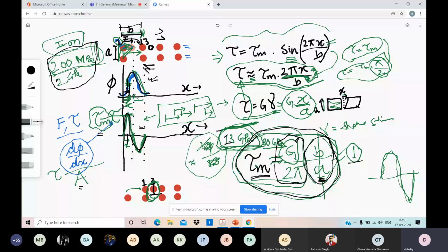And typically, if you see the structural steels that are used, which contain carbon, which gives additional strengthening compared to iron, there the typical yield strength value is 300 to 500, 600 MPa. Above 600 MPa, it is considered to be high strength. But to cause plastic deformation, you need a stress of 13 GPa as per this derivation. And then I asked, what causes this discrepancy?